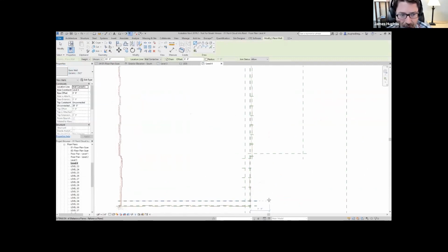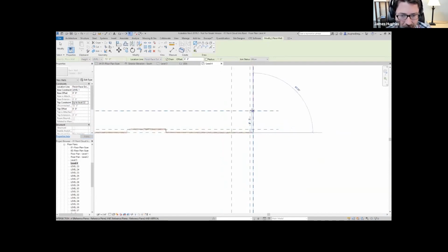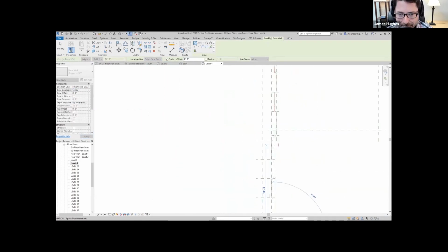And then we can start to make choices about what the wall is going to be. And you do not have to guess correctly. You should justify it and set its height before you begin. Here I goofed up because the level numbers are wrong, but we'll go from level 1 to pretty high. Start it exactly in the corner. You get a nice hard snap.